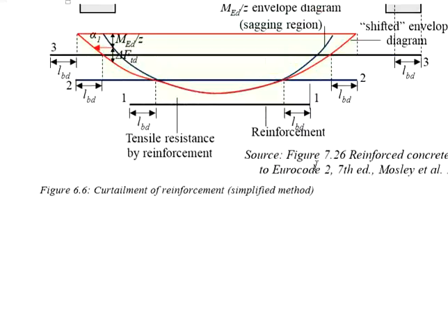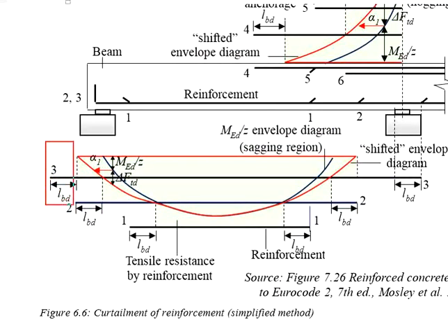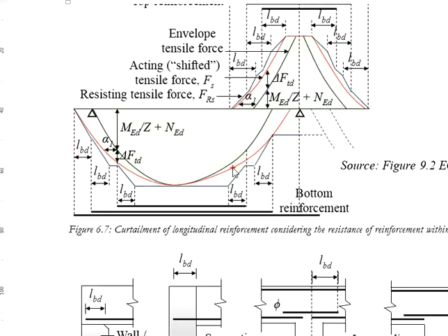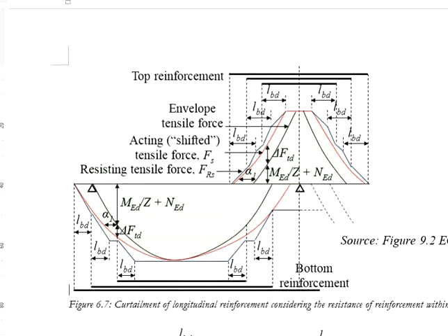Specifically, we are talking about an additional offset here, which has already been bypassed by the accurate model by the Eurocode 2. Then we look into the hogging moment section. From the bending moment diagram, you will do the conversions by using the moment divided by the section modulus, taking into considerations if there is any axial force acting onto the beam.